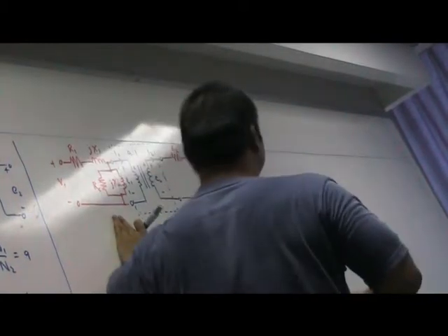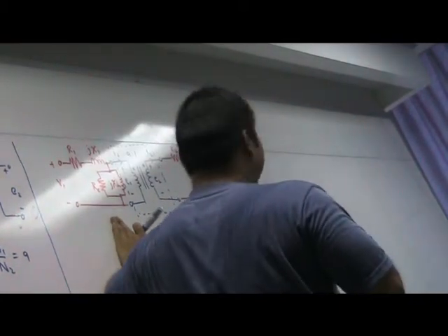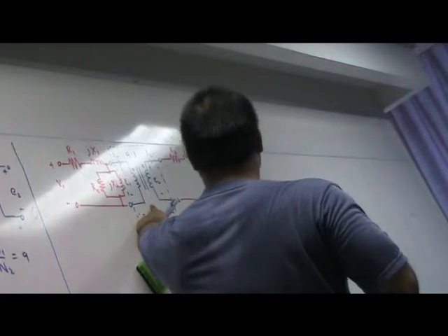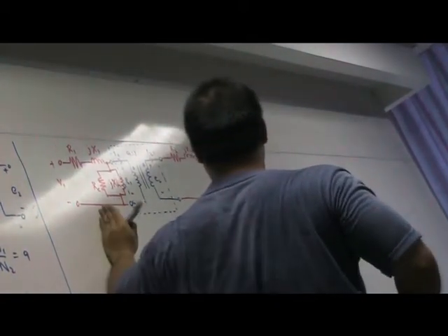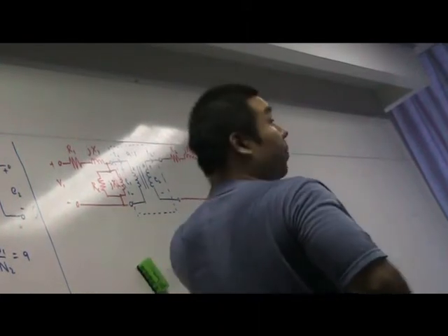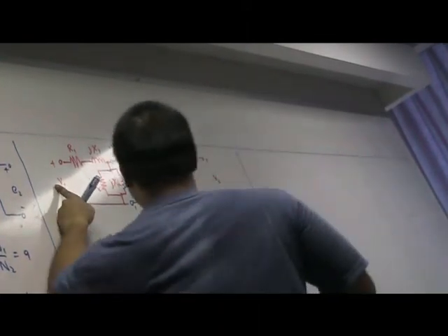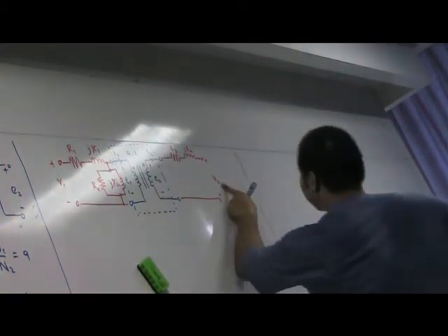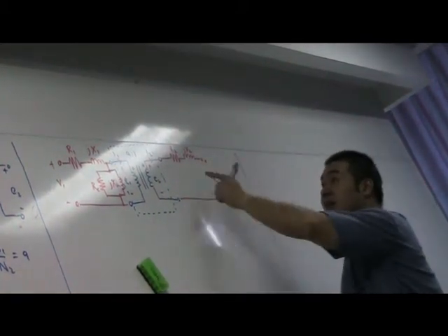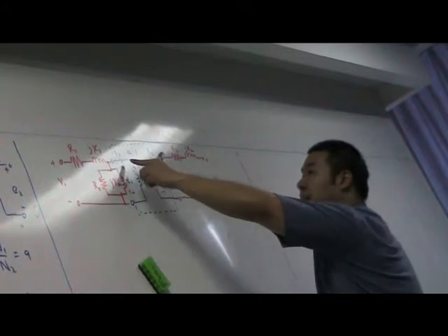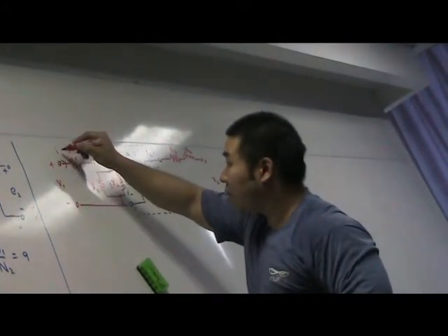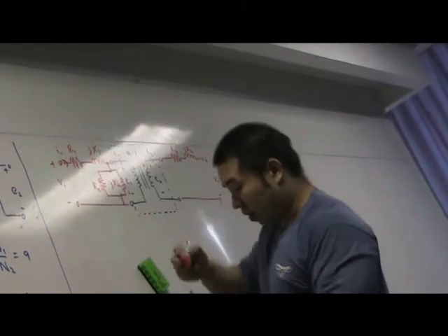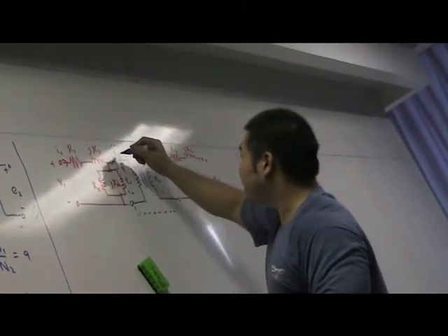And this is the circuit for the practical transformer. So you have the ideal transformer, everything in blue is ideal, and all the non-idealities are shown in red. V1 is the input voltage, V2 is your output voltage, I2 is your output current, and I1 is now the primary side current. If I call this I1, then this one will be IP.